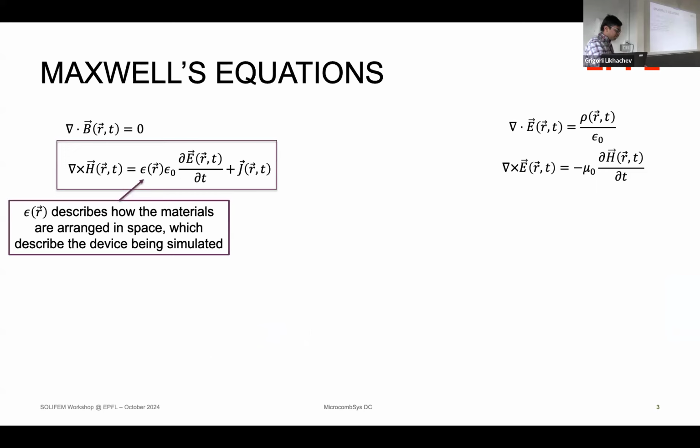When you have any photonic device on the chip, what you're basically doing is you have some amorphous dielectric material that is immersed in another type of material. For example, a silicon nitride waveguide is present around silicon oxide. So the permittivity is the thing that is varying in this geometry on the chip. Light is just going to see different refractive indexes, and that is what we need to model in 3D simulations. Whenever you do any photonic component or design, you're just playing around with the permittivity of the material, and that is the parameter that you see over here that changes.